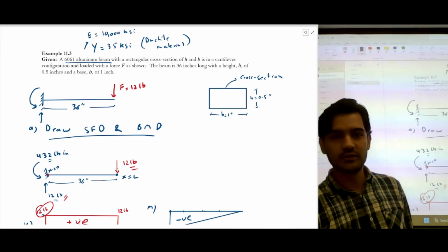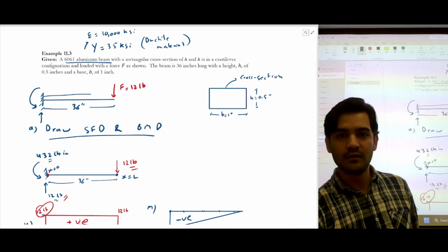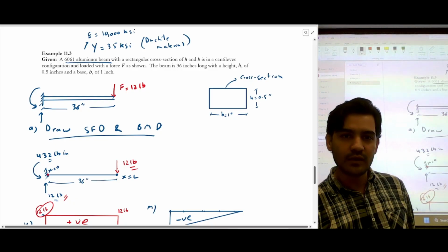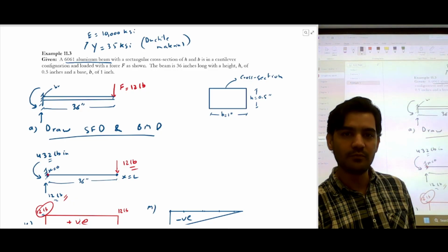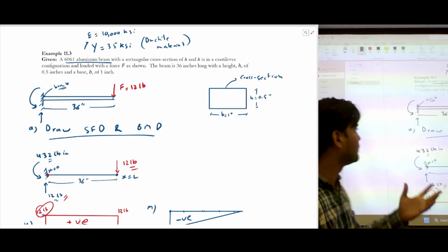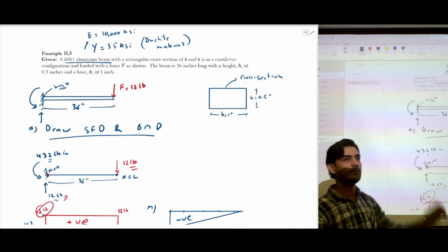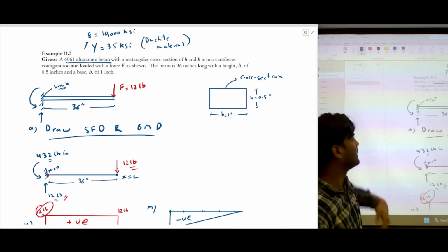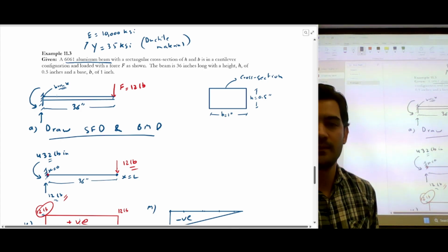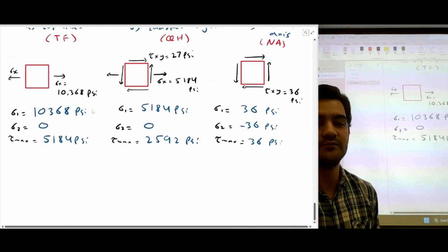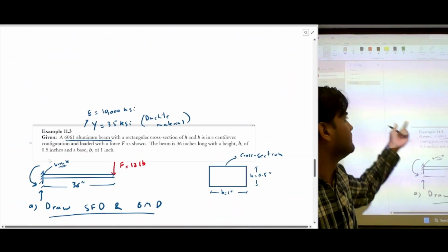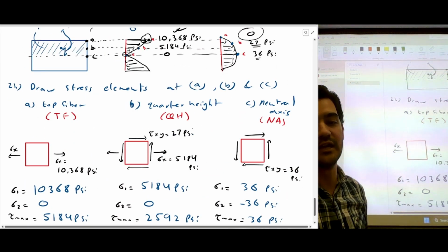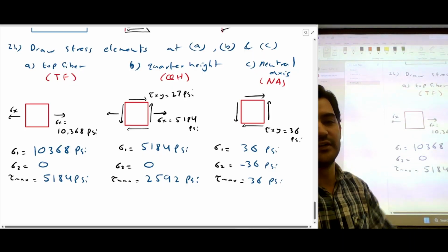So if I want to draw the entire beam, that's where it will break, because that's where we are getting the maximum stresses. That's the first point of break, and then the entire thing will break. But we will see if we will observe the yielding or not. It will yield, but then it will break because it's a ductile material. So it will fracture after deforming a bit.